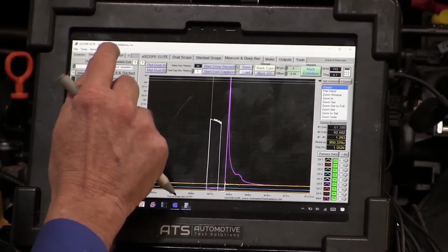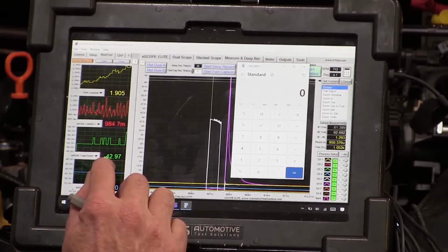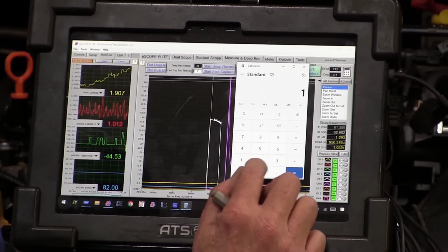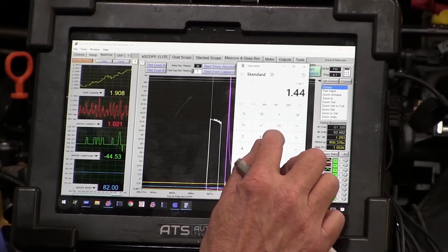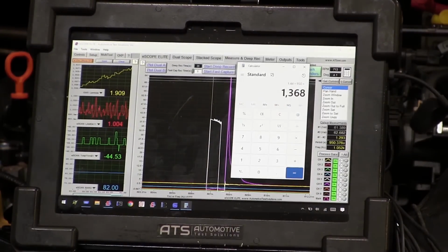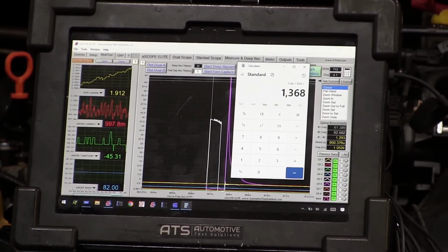Okay, so we're going to go over and get the multi-tool. I'm taking away 44% trim, 44% trim. So I'm going to put 1.44 and I'm going to multiply it by 950, which is my on time. That's what the computer figured its base injection on time is. That's a lot of injector on time, guys. That's a millisecond, 1.3, 1.4 almost. That's like port injection on time.